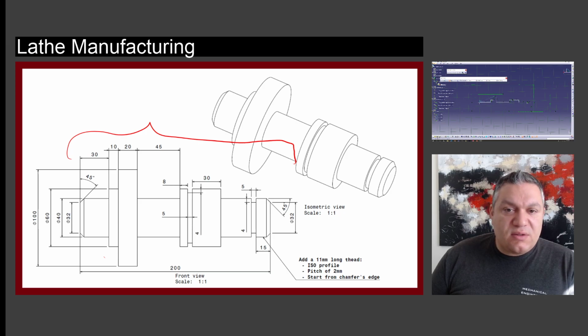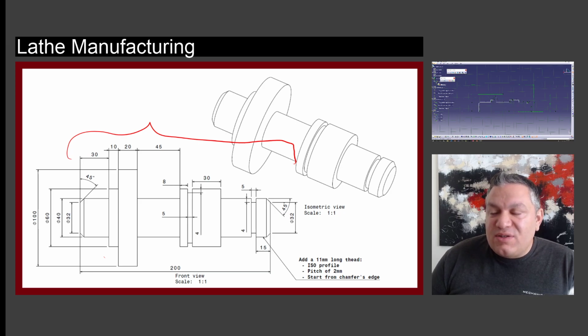Very obviously this is not, okay, I don't want any constraints here because this is going to confuse me. So although it looks like it's doing a constraint, because I click this one, it's not going to do it. And then here. Okay, so I've created what I think looks like the profile. Now what we're going to do is we're going to start creating some dimensions and making sure this is iso-constraint.